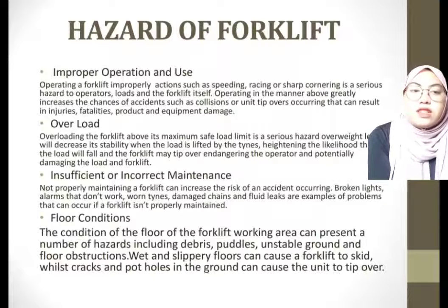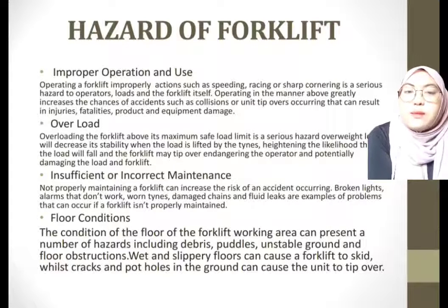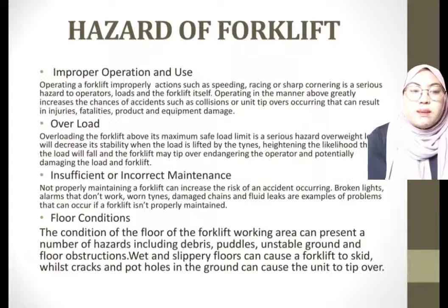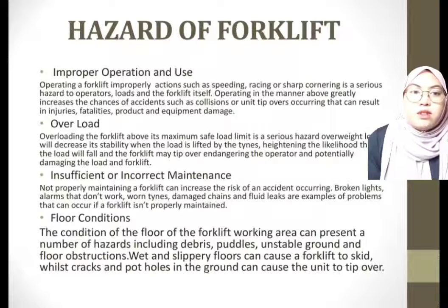Lastly is floor condition. The condition of the floor of the forklift working area can present a number of hazards, including debris, puddles, unstable surfaces, and floor obstructions. Wet and slippery floors can cause a forklift to skid. Cracks and potholes in the ground can cause the unit to tip over.